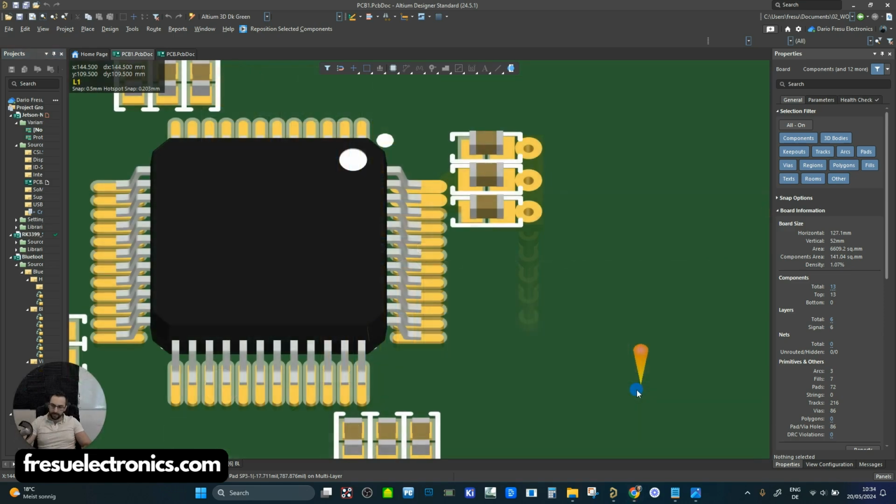So now let's look at how choosing the right strategy for the decoupling capacitors and also their placement is going to have an impact on radiated emissions. Really, the problem comes from the inductive loop that we create. So we know, for example, this is a power pin and this is the ground pin. The loop that we create goes from the power pin and the capacitor, but also through the return path. It goes through the via there, connects to the return reference plane, and then goes back here. There will be another via, and it will go back to the ground pin.